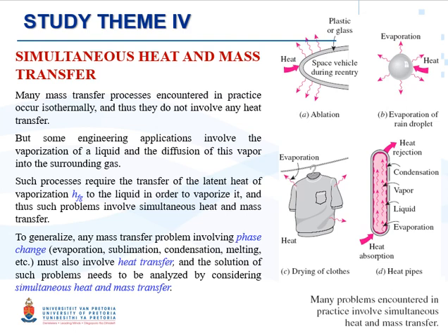It's one of the best examples of it. Such processes require the transfer of the latent heat of vaporization, h_fg, to the liquid first in order to vaporize it, and then such problems involve simultaneous heat and mass transfer. To generalize, any mass transfer problem involving phase change like evaporation, condensation, melting must also involve heat transfer, and the solution of such problems needs to be analyzed by considering simultaneous heat and mass transfer.